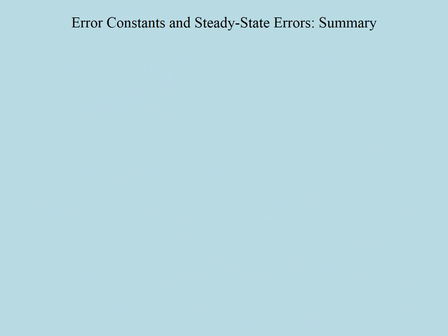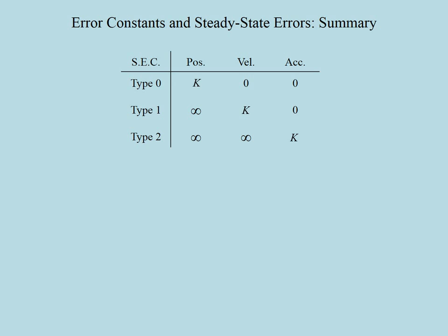We can summarize all these results in 2 tables. The first one tabulates the static error constants. As mentioned earlier, a given error constant improves with increasing system type. That is, as you go down the table. Correspondingly, for a fixed type, the constant corresponding to a more complex input is decreasing. That is, you have smaller error constants as you move towards the right in the table.